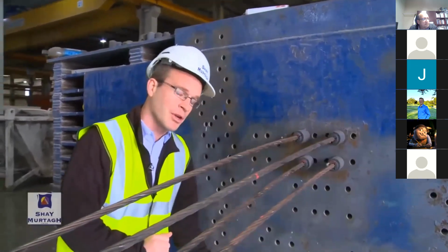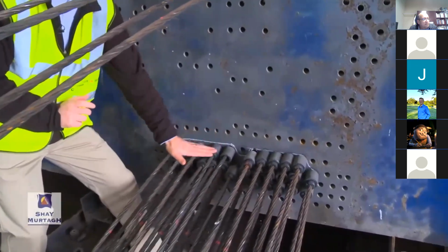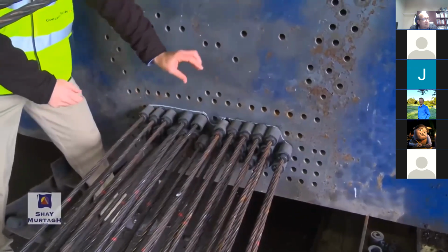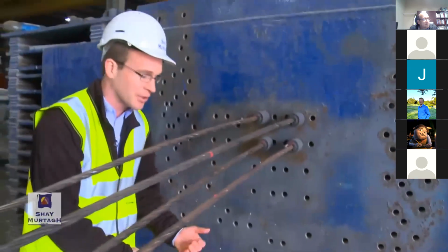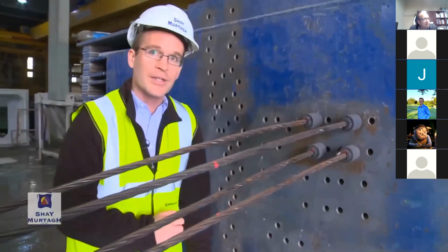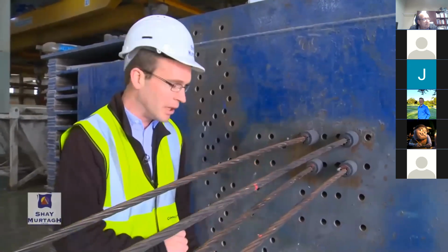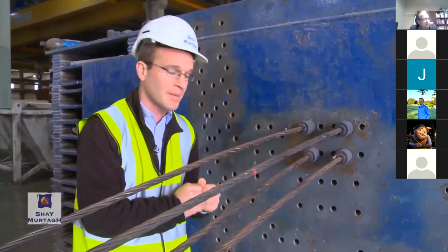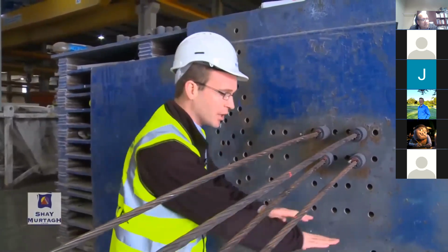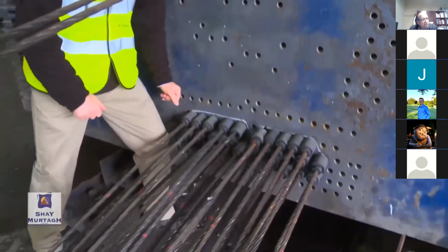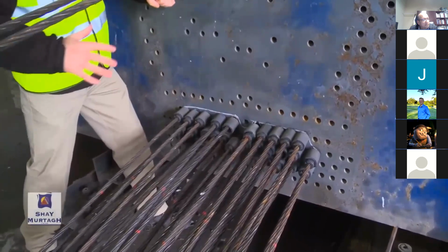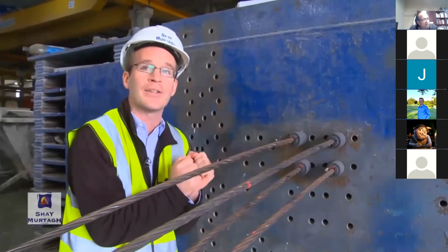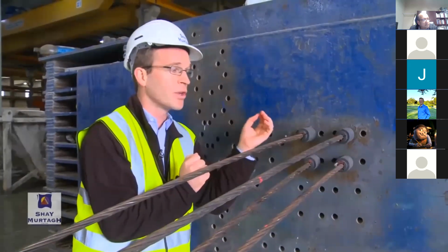Now, notice with this strand layout, there's a far larger number of strands closer to the bottom of the beam. The soffit of the beam would be just 50 mil underneath the actual bottom of the strand, 50 or 60 mil. The reason for that is not only do we want to apply compression to the beam, we also want to apply a bending moment to the beam as a result of the pre-stressing operation. Because that overall position of the strand is eccentric, it's removed from the centroid of the beam, that enables that application of pre-stress to also apply a bending moment that will act against and relieve the bending moment that results from the applied loads.